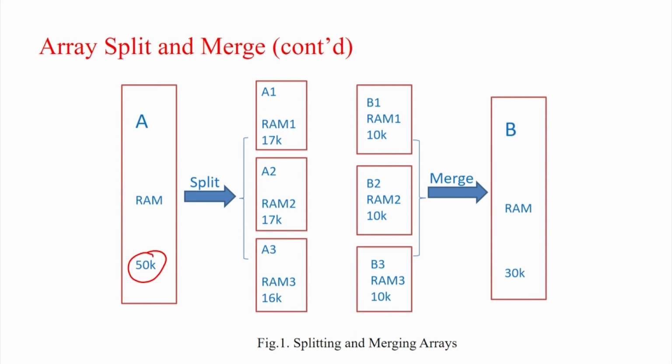So, it is better to split it into small arrays so that you can distribute your access locally. All the local accesses are mapped to this block, so you can partition it properly and infer RAM out of this block and this block. Whereas if you just try to map the big array, it probably cannot be mapped to a single RAM because of multiple accesses. So, if you split it according to their access, so that non overlapping accesses are clubbed together, then you can infer RAM even with multiple accesses.